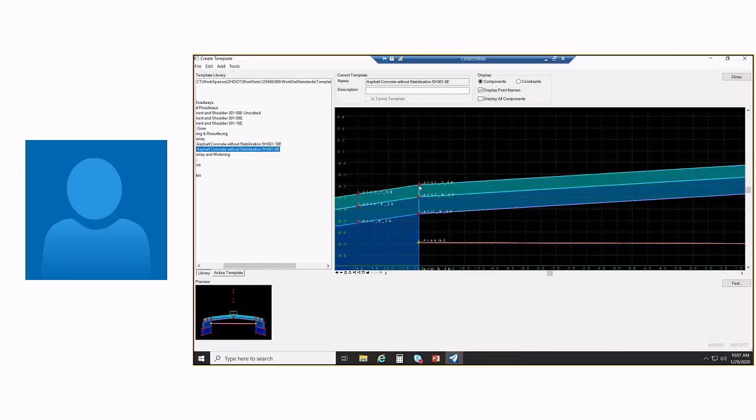And in the point controls, I don't think there's any way to give a vertical parameter or something like that. I can't just assign this point because everything's defined as far as the constraints from the top down. So if I assign that, it's just going to move it up. The other points aren't in relation to that.